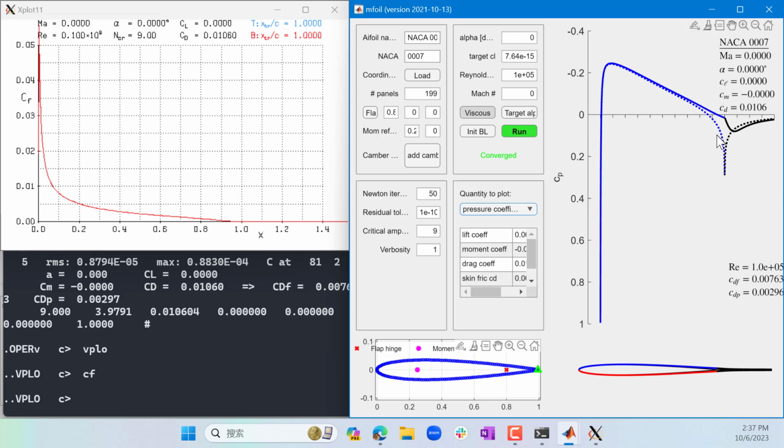Can somebody think about this? The viscous flow has a lower pressure near the trailing edge, right? So that means the viscous flow is sucking more at the trailing edge. Think about what is the normal direction at the trailing edge. It's pointed slightly towards behind the airplane, right? So even the pressure, the viscous flow causes a pressure difference which contributes also to the drag.